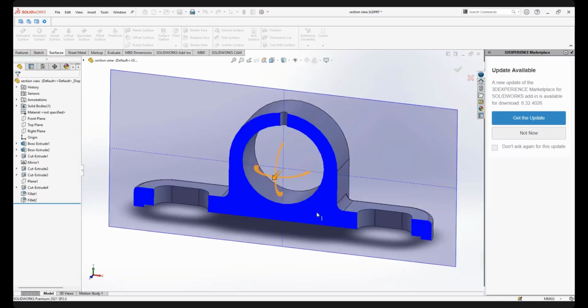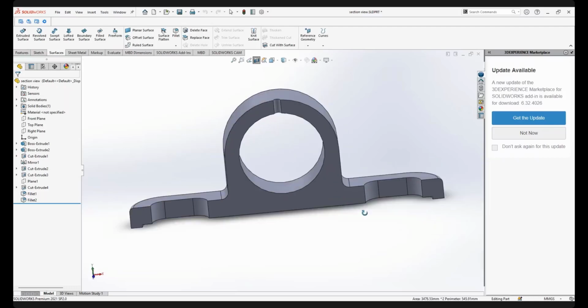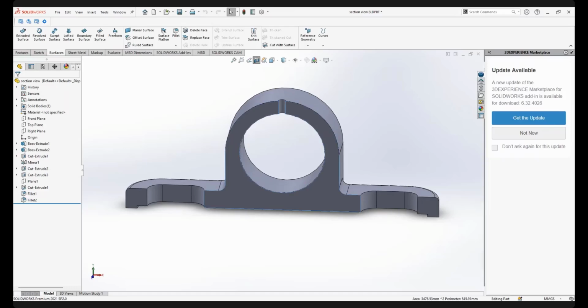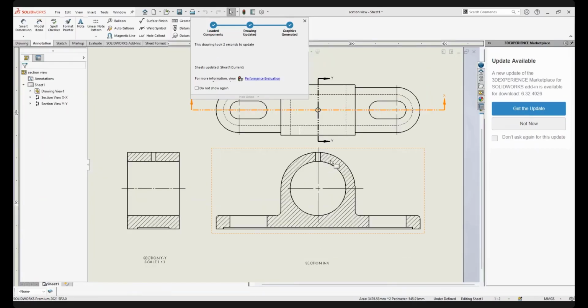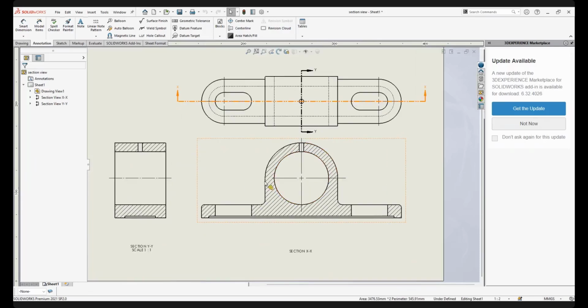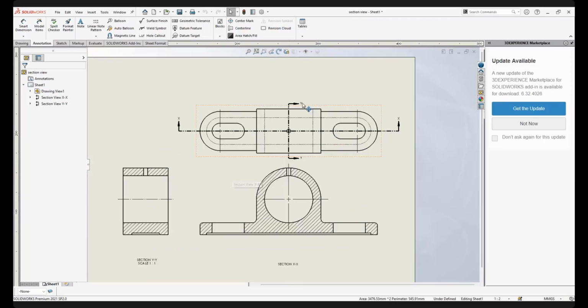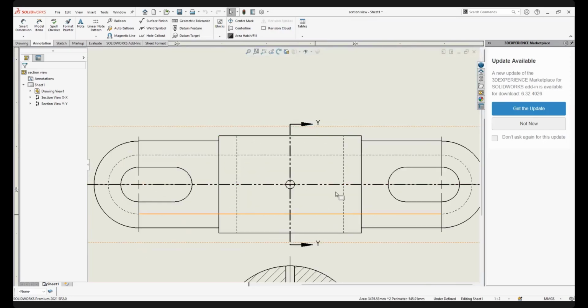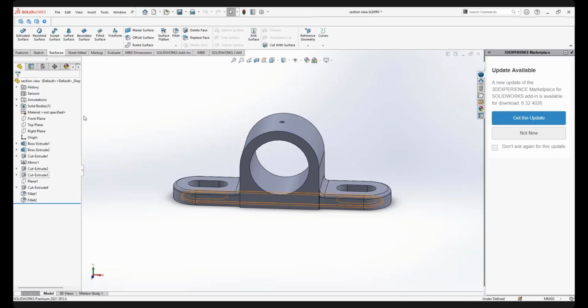Good. So whatever you draw as the front view, you just drag from your solid part modeling, because everything is automatically done. Okay, front view with hatching. Now this is the answer front view, because section X is like that, and you bring the front view with hatching. But this one must be complete with the dimensions. Section YY, the part we are asking about, because section YY is cutting like this, right? So it means in your part modeling, section YY is this one.